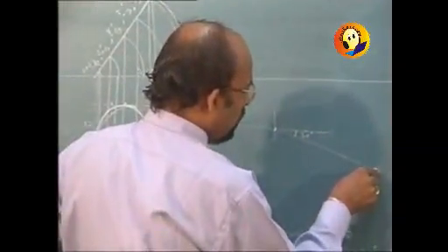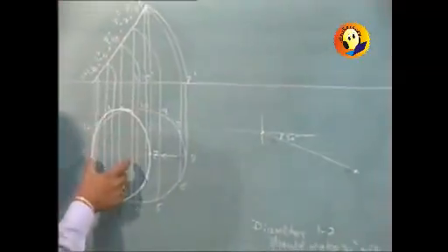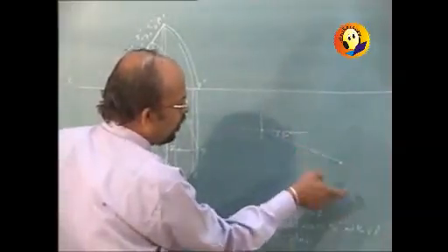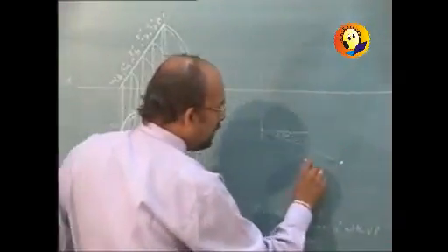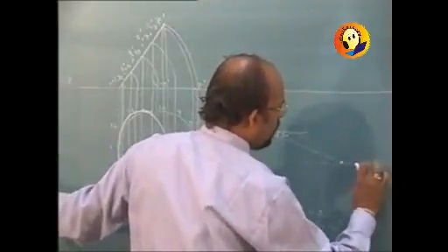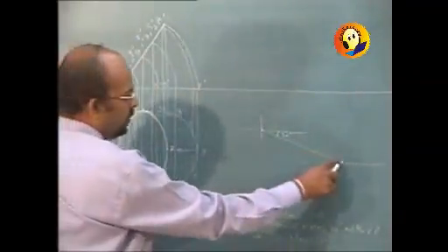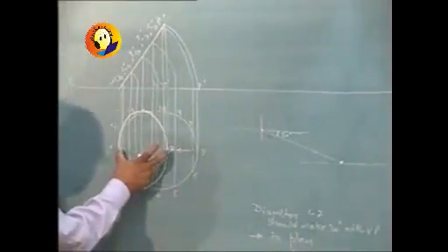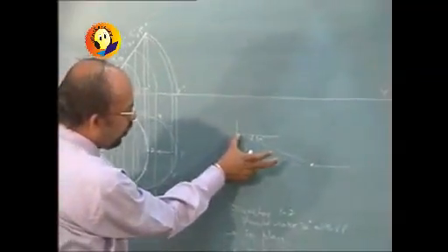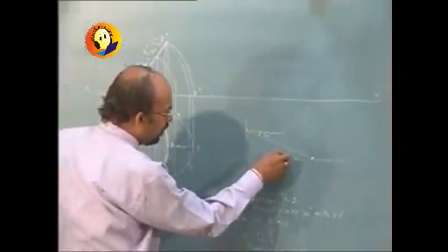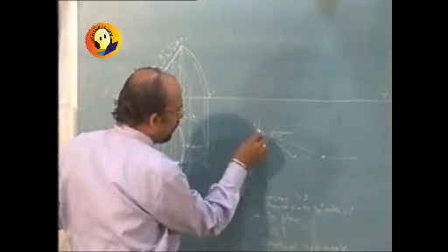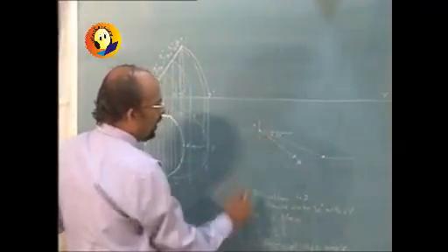So we can mark the actual diameter of it, and then get the path. Our standard construction. So this was the actual diameter. And now take the new diameter that we have got, new length of 1/7, and from this fixed point cut one arc, and we get the new position for 1/7, the new angle.